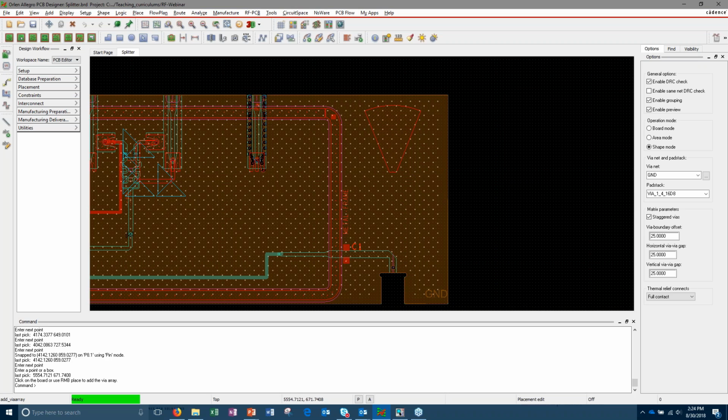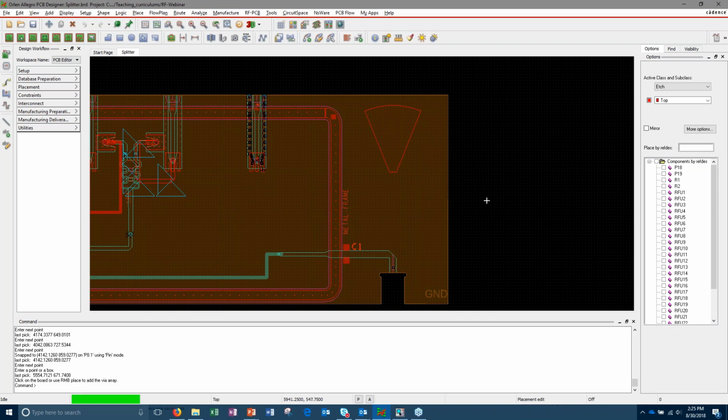It's going to go out there and calculate. And what you're seeing is a highlight. This is a preempt of what's going to happen. If I click on that shape again, it's going to set these all down. When it sets it down, it'll immediately go into a DFM check to make sure there's no DRCs being created in there. And it'll remove those vias that create it. So you can look in there, and some of those vias look like they're going to be right on top of my etch. But it would remove those. If I click on that, it's going to take a little time for that calculation. So at this point here, I'm just going to cancel out of it. But the second click would set it down and remove all those DRCs.